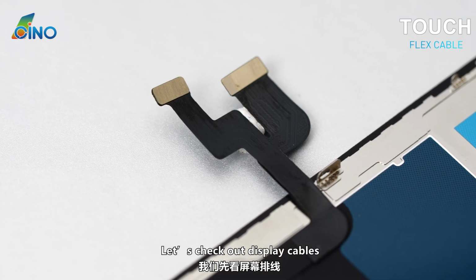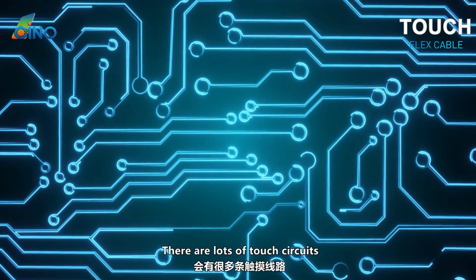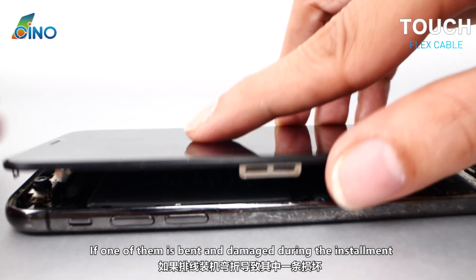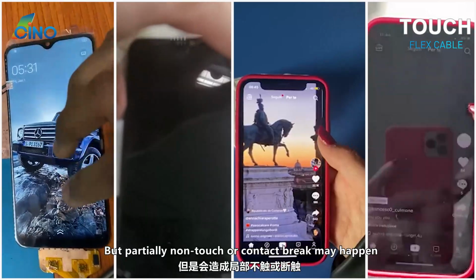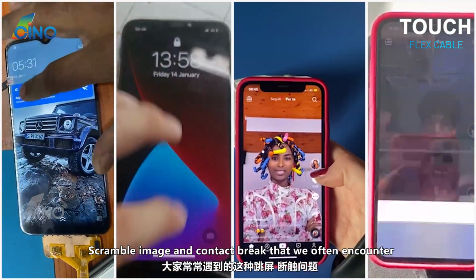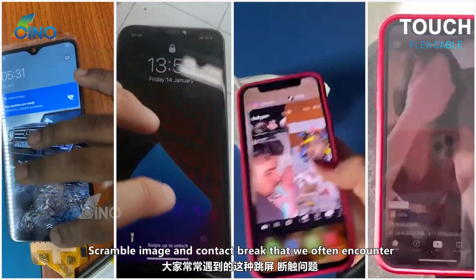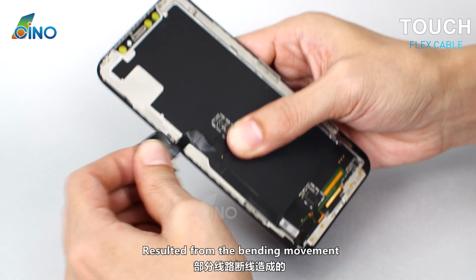Let's check out display cables. In just one single cable, there are lots of touch circuits. If one of them is bent and damaged during installation, its touch can still work, but partial non-touch or contact break may happen. Scrambled image and contact break that we often encounter are mainly because of partially broken cables resulting from bending.